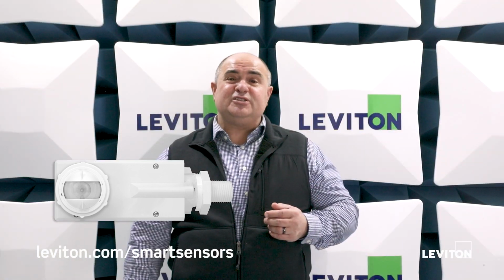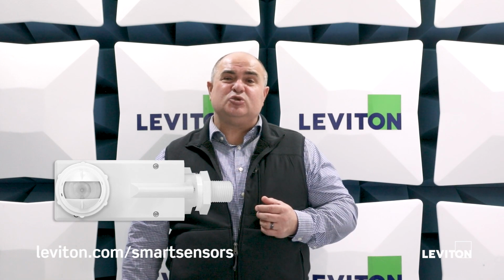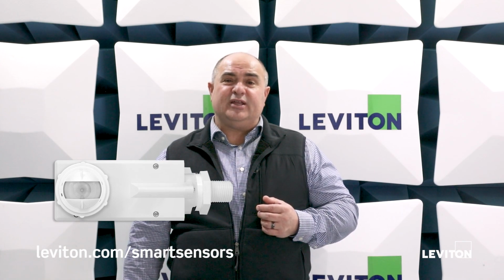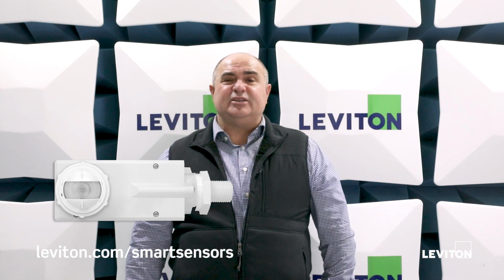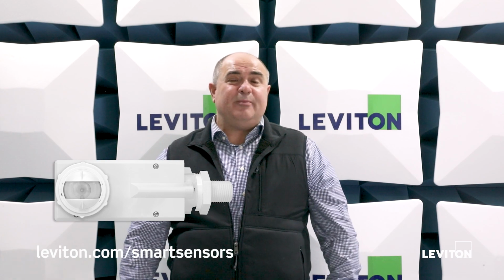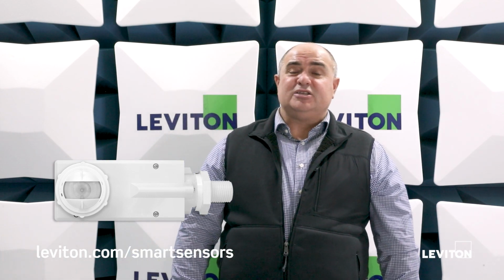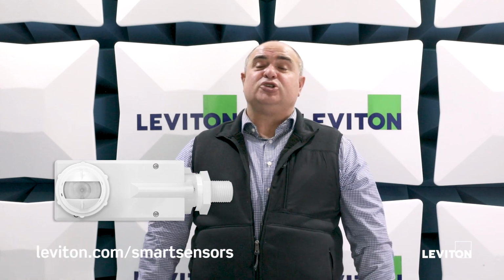How about daylight harvesting? Well, the warehouse areas will have applications where you will require daylight harvesting if they have skylights, and that is also integrated into these smart sensors. So again, a very simple solution, but the key to this is it does work with the same smart sensor app to program the fixture. What does that mean? Well, that means the warehouse lighting also has the ability to have partial off or even the partial on.